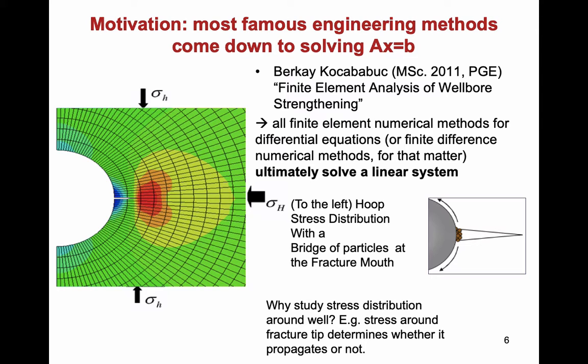Okay? That creates problems. Because of that, along this larger stress direction, I might alleviate stress by fracturing. Okay, and that's essentially hydraulic fracturing. It often happens when the pressure in the fluid that is in the wellbore overcomes the smaller of the stresses. This smaller one right here. Okay, and the moment that fluid pressure, which acts in all directions, overcomes the smaller stress, I crack. Okay, so monitoring the stresses, and especially the stress field at this fracture tip, determines how the fracture will propagate further into the reservoir.